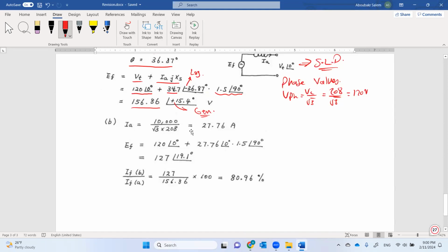we can say that the second current equals the same amount of power, since the power is constant, divided by root 3 times 208. So this is the amount of current. He used here the power and the same volt, and he substituted the power factor as unity. Let me write the relation, guys, since the textbook solution is not clear enough.